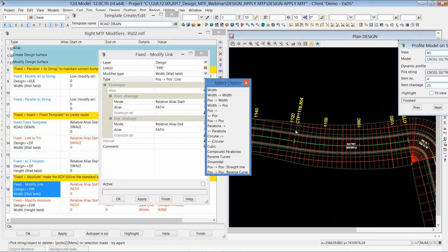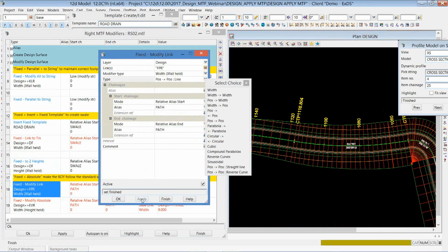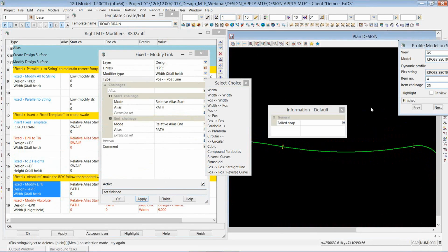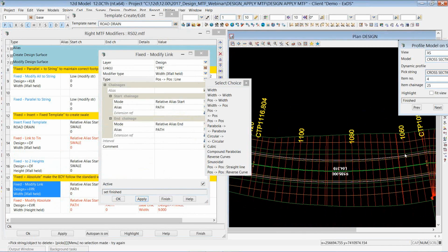Everyone knows no one walks around the corners. Everyone walks straight across the path there, across the grass. So let's just make it a straight line. So I'm going to run this command, and you'll notice that obviously it will do just that. Between those changes, it's made the path go exactly straight where I asked it to be. But the problem with that is that every other string external of that, including my boundary and the interfacing, has all moved because the string on the inside of the template or the snippet has been adjusted. So how can we control that a little bit better?